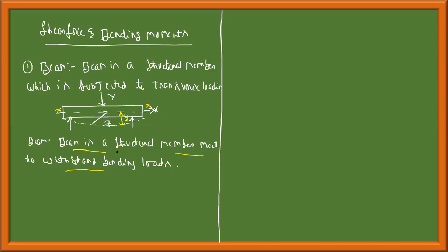And the different types of beams are, I'll call this types of beams. Generally it is simply supported, and based on the nature of support and loading we classify the beams, but he has given it in a more elaborated way. We'll discuss this. First type, statically determinate beams. That is, beams for which the number of unknowns can be easily found by using three equilibrium equations.